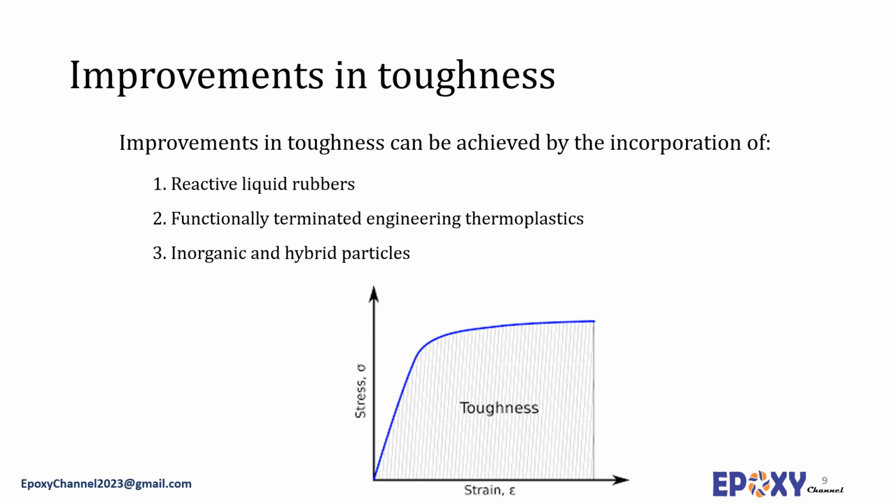Toughened structural adhesives generally have two distinct phases. The larger phase is the base resin and the minor phase consists of small, on the order of 1 micrometer in diameter, distributed elastomeric entities. The addition of the second phase significantly improves fracture toughness by providing crack pinning and stress distribution mechanisms within the material. The elastomeric particulate phase is often thought of as a crack stopper for improving fracture toughness.